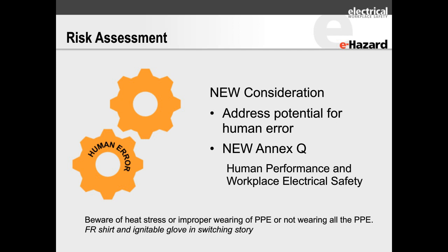And I like to think about it that way because we match it to the hazard, whereas in flash fire, it's just a very generic low-level protection so that if you do get in a flash fire, the clothing doesn't increase your injury and will provide some protection. But we try to match PPE in arc flash, so it's a little different than a normal PPE. It's kind of like using something in between, say, a flash fire garment and a firefighter's uniform, which is designed to totally protect them from being in a fire. At some point, a flashover may not totally protect them, but it's usually very, very protective. And arc flash is very much the same way.